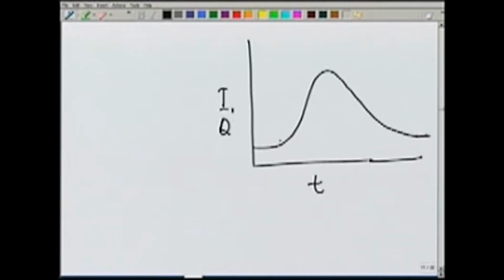If we plot the inflow and outflow, assuming that it returns back to its original position, and as we said there will be a peak attenuation and lag, this point where the inflow and outflow intersect typically will have the largest outflow, or the outflow will be maximum and the storage also.